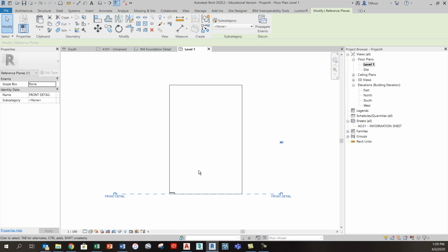When I'm working away in Revit in a floor plan view, Revit just makes the assumption that all the extrusions, for example, my walls or my floors or my roofs would just be based on that particular level. But whenever I need to create something from an elevation or a section view, Revit needs some more information about where in that infinite horizontal plane to place the base profile for that extrusion.